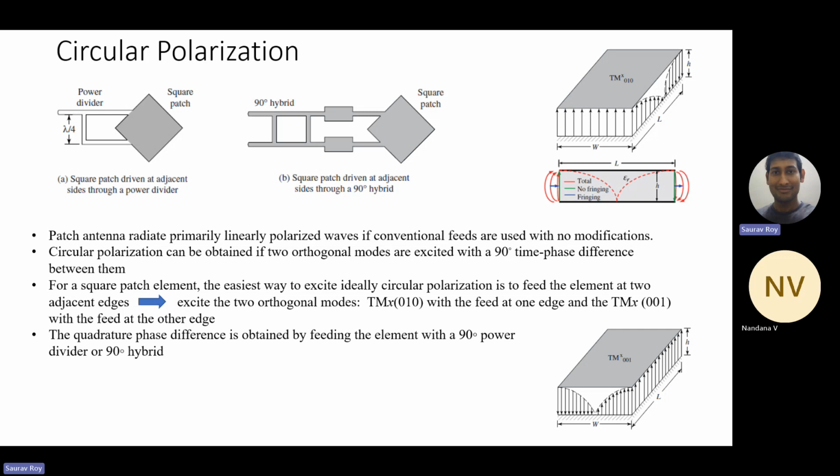So if that is the situation, then how will our mobile phone receive? There will be a lot of polarization mismatch, right? Unless the transmitter antenna has a circular polarization that will transmit in both planes, both E plane and H plane. If that happens, then whatever the location or alignment of the receiver antenna, it will not matter that much.